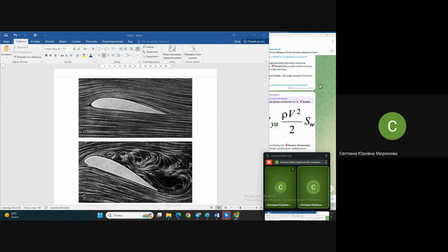We have special laminarizing devices. For instance, it may be organized as additional downwashing, let's say, of some area. For instance, you have some device inside of the wing which downwashes additionally here. It's like adding little jet streams appearing here in order to laminarize downwashing in this area, in the risk area.